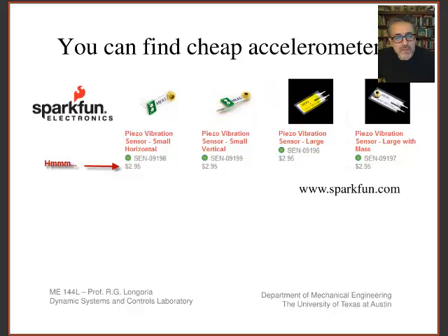I've played around with some of these, and we've used them in the lab also, actually. But what you have to do is build a signal conditioning circuit to measure them, because these are piezoelectric. They're not capacitive. So for the piezoelectric sensors you need what's called a charge amplifier to measure the output of these. And so it makes for a nice little lab, but we're not going to do that in this lab, or we may not do that in this lab.